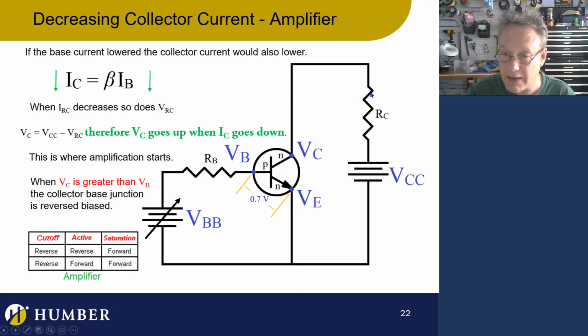Again, say this is 100 milliamps when it's fully on, then I know my gain is 100, right? So I need 1 milliamp to go through here to fully close this switch and get 100 milliamps going through. But if I only put half a milliamp through, or 500 microamps, then it's going to be 50 milliamps going through here. And whatever the load is, a light, a motor, a solenoid, it'll be going at half the current. Pretty cool.